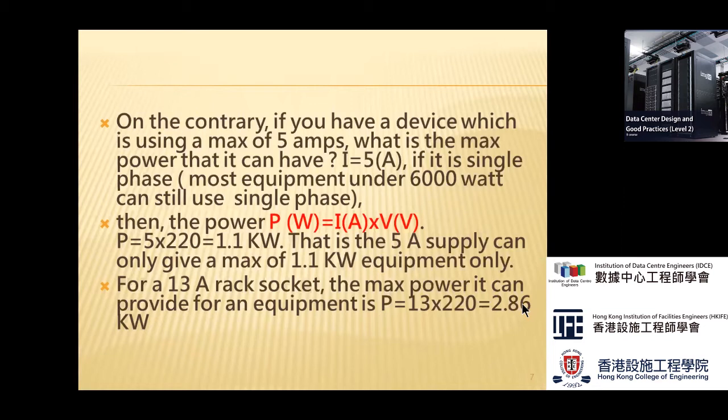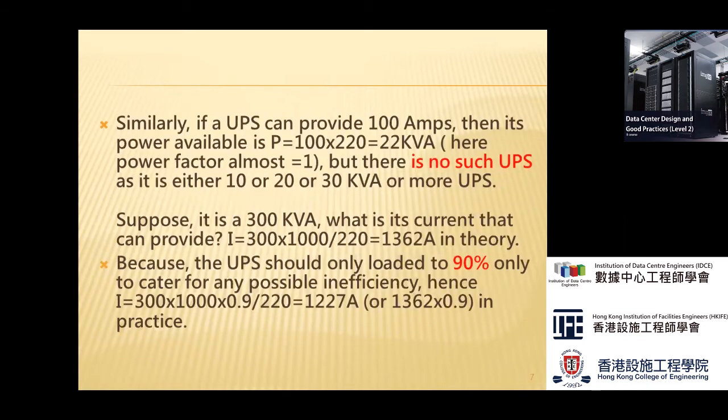So anything more than 6 kilowatts, you have to use individual radial circuits. Single supply, single equipment. That's for most of these high density racks as well. Whether it's 8, 10, 20 or 40 kilowatts, you use one single cable to provide one machine only.